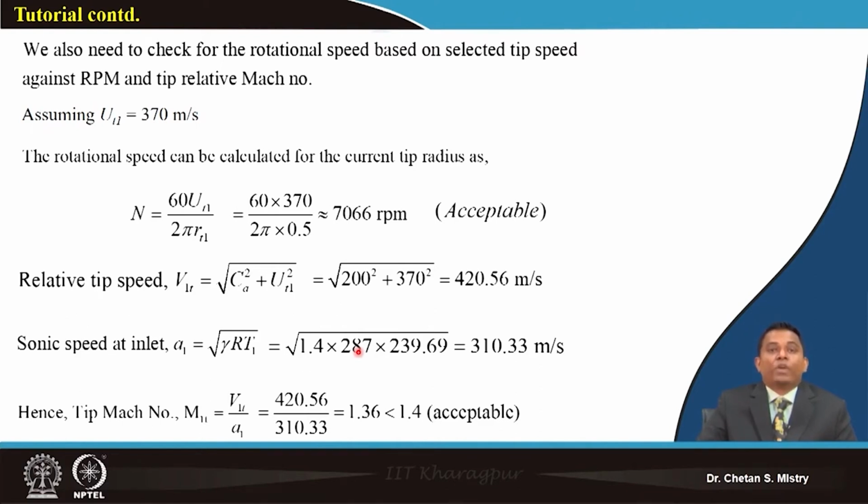So now we are fixing our axial velocity, we are fixing our peripheral speed. Many times, based on certain assumptions, you can go forward. It says it should not exceed 8000 rpm. You have that flexibility. You can assume the speed to be say 7500 rpm and you can do the calculation. There is nothing wrong in that. This is based on a few of our iterations, and that's the reason why we are straightaway putting our peripheral speed as say 370 meter per second.